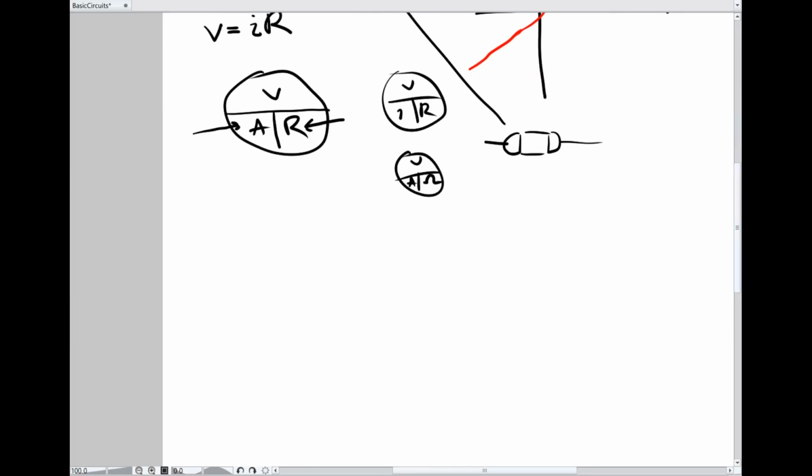So what's my next component? Well, my next component is called a dependent source. So a dependent source, usually drawn with a diamond shape, is some sort of source that depends on some other measurable quantity somewhere else in the circuit. And these are usually used to make a linear approximation of some sort of amplification device, like a transistor.